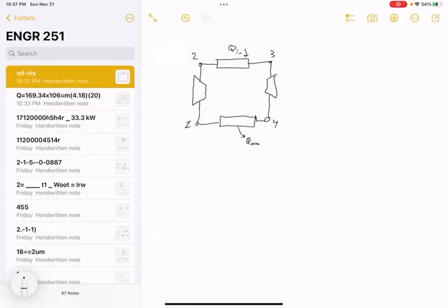Now, something to note, just like in the Rankine cycle, we do have a work output here. But the compression process for something with a high specific volume like air is really, really demanding energy-wise. So a lot of this work out is going to get sent back to the compressor just to drive the compressor. So how it works is the compressor, just like we saw in the other question with a pump, instead of a compressor, is being powered by taking some of the work that the turbine does and using it for itself. And the rest of the work is the net work, and that's what you can do other things with.